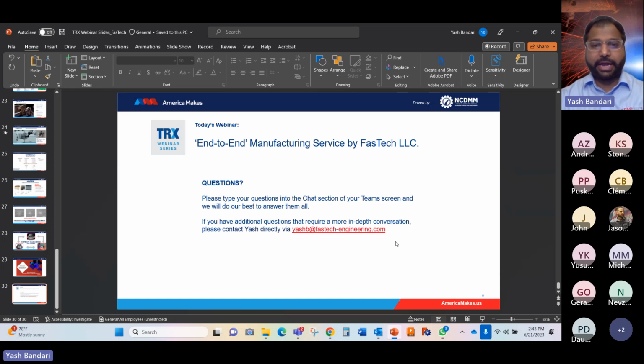In terms of qualification, it's a big buzzword right now in additive manufacture. Is it qualifying the process, or is it qualifying the material? Qualifying the additive system as well. Which is important actually? I guess all are important, but people who come from a specific background define which is important for them, and we pick them, and then we do a round robin study, print a lot of samples, take a lot of coupons, and then test them, right from the chemistry standpoint. We validate the printing chemistry is the same as what we get in the wire form. We look at the hardness, the fatigue properties, yield strengths, elongations, ductility, all of these things which are important for the product to be qualified by the customer.